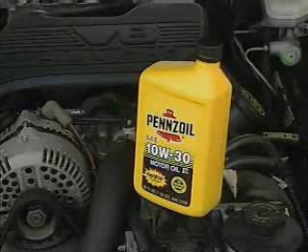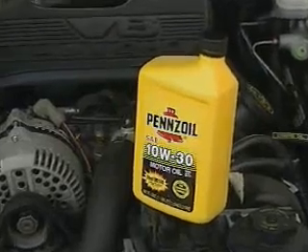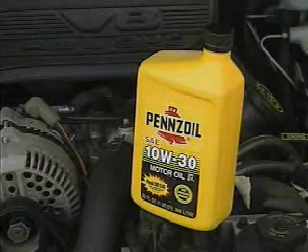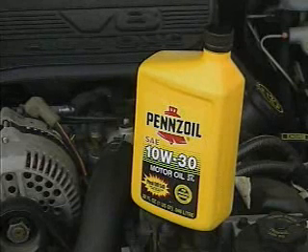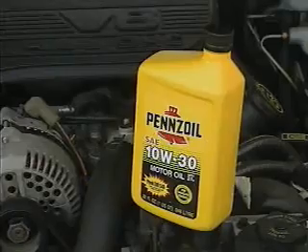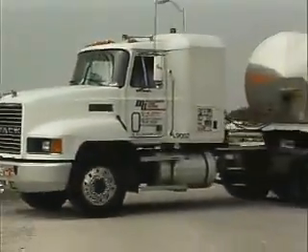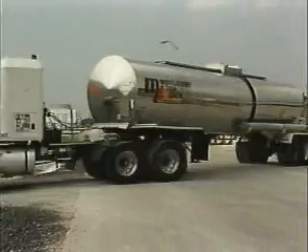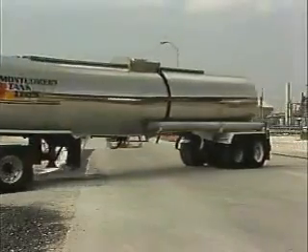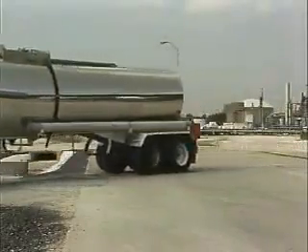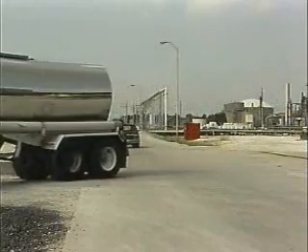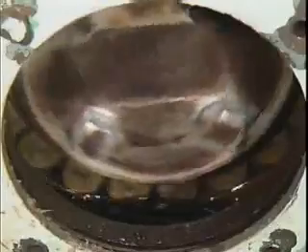Engine or motor oils contain additives that enable the oils to be used in different types of operating conditions and in different types of engines, such as diesel engines and gasoline engines. This tank truck, for example, uses an engine oil that's specifically designed for heavy-duty diesel engines and relatively severe working conditions. There are many different methods for lubricating equipment with oil. The method that's used generally depends on the equipment that's being lubricated.